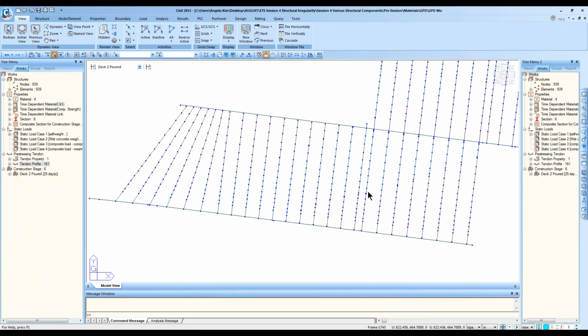However, as you know, for the grillage analysis approach, both the girder and especially the deck portion are modeled using the beam element. And beam element is only in one longitudinal direction. So when the deck is modeled using the beam element, there's nothing that actually represents the deck in the transverse direction.